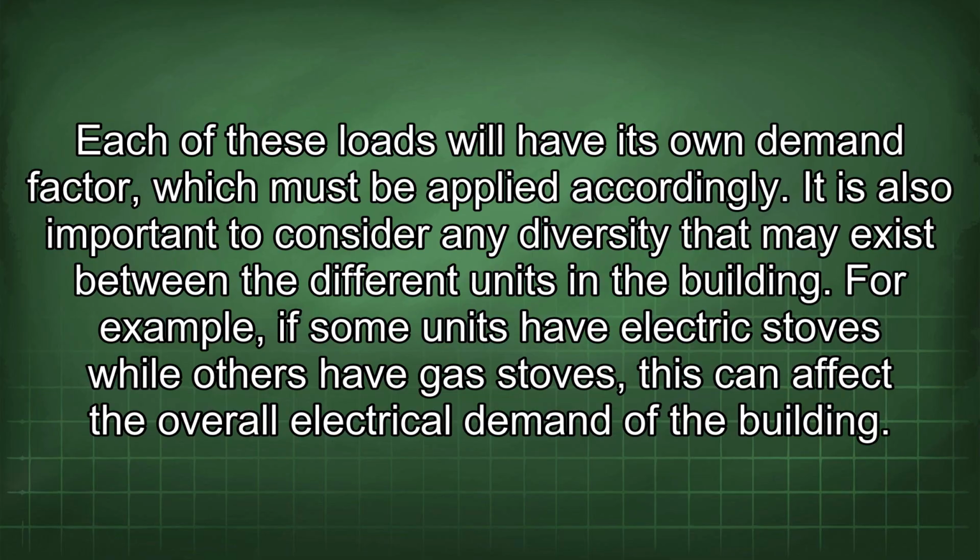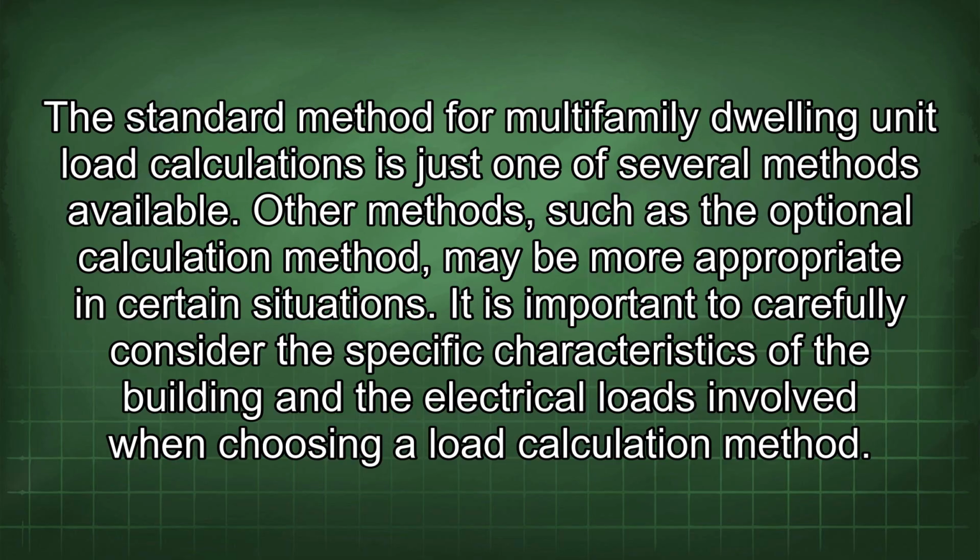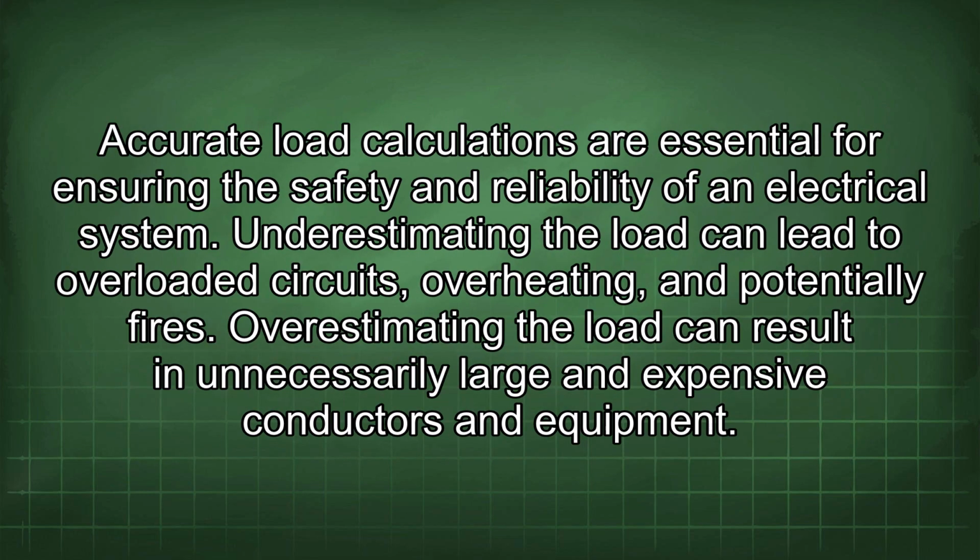The standard method for multifamily dwelling unit load calculations is just one of several methods available. Other methods, such as the optional calculation method, may be more appropriate in certain situations. It is important to carefully consider the specific characteristics of the building and the electrical loads involved when choosing a load calculation method. Accurate load calculations are essential for ensuring the safety and reliability of an electrical system.